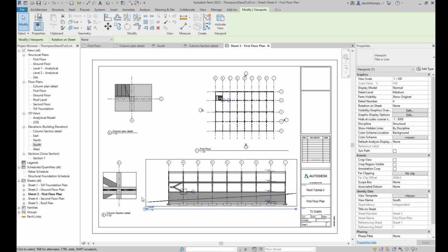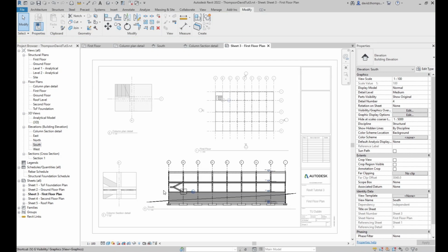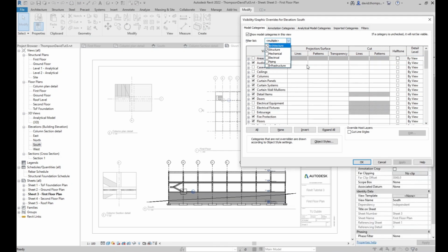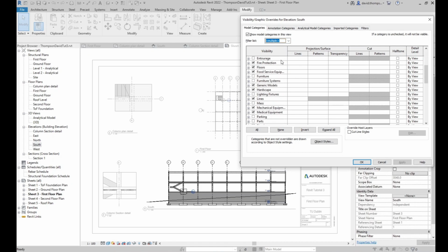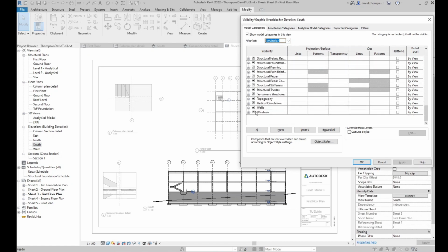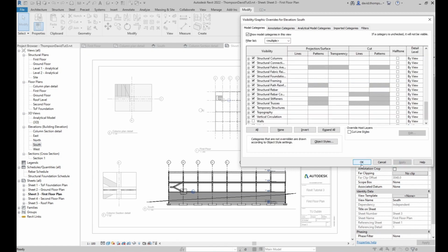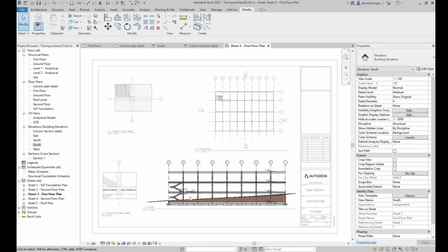Actually, what we might do again, just to balance these, I'll click into this, and we'll turn off that wall view. Sorry, we'll remove the wall so we can match the details in the callout. So we'll bring up the architectural, just make sure we have everything, and actually it's within the structural, so we didn't need to do that, but we'll untick walls, click apply, click OK, and you see now the wall is gone. So now we'll see this view here matches what the view here is going to be, so this makes things a little bit clearer.